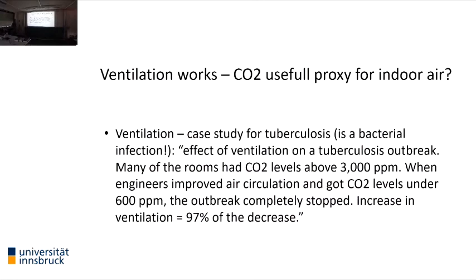So there have also been case studies long ago on other airborne transmissions, TB, tuberculosis. It's a bacterial infection, but also highly infectious as airborne. And what they saw is they also got these super spreading events in indoor places, in that case in hospitals. And they realized it also had to do with dilution somehow. And so they realized when CO2 concentrations indoors were above 3,000 ppm, this is also a limit where indoor air quality policies would say you should open the windows or should vent because of other pollution that could reach levels that you don't want to be exposed to for a long time. But anyway, they saw that at 3,000 ppm they started having these cluster outbreaks of TB, and then they started to really dilute and vent indoor air.